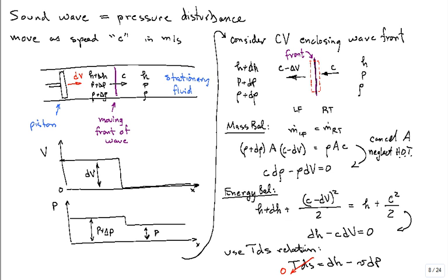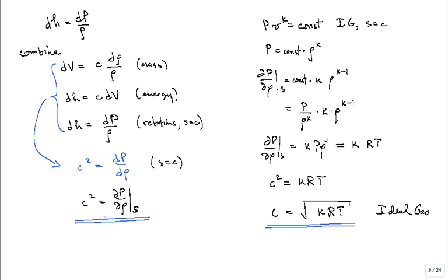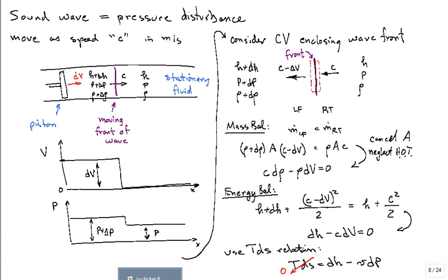The equation that we derive is a little bit of a derivation. Let me give you a quick go through, but right here is the bottom line equation where the speed of sound squared is equal to the rate of change of pressure with respect to density holding S constant. All right, so what you do, and it's outlined in the textbook, is think about a piston that abruptly moves in a tube containing stationary fluid. It produces a pressure pulse.